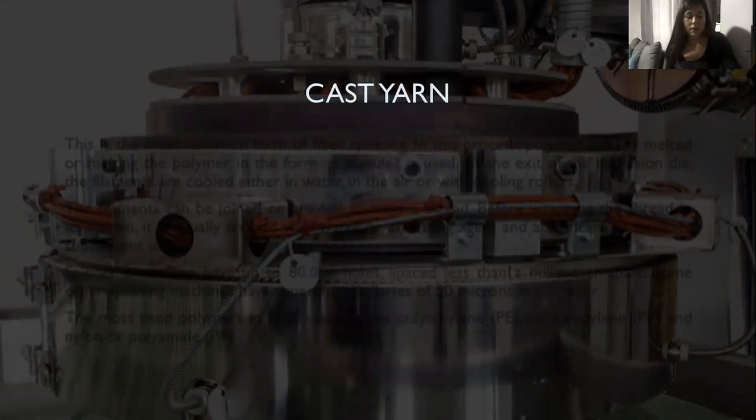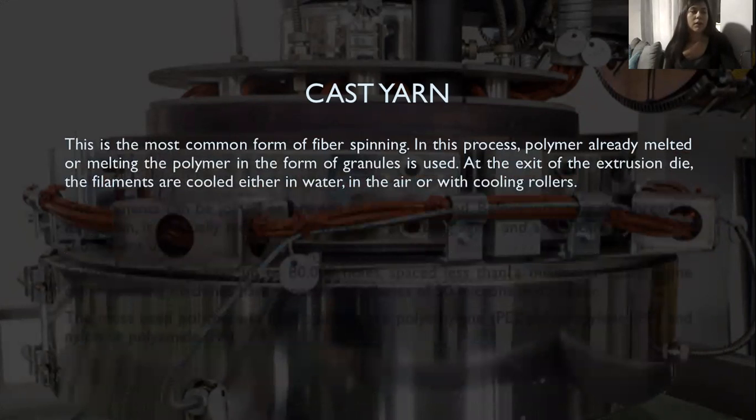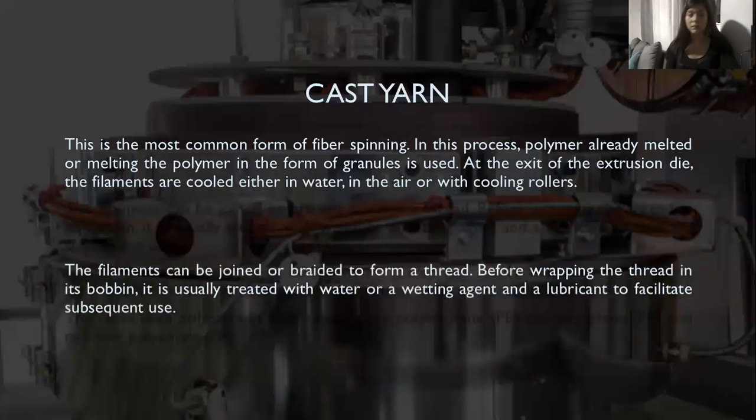We will start by explaining the melt spinning process. This is the most common for fiber spinning. In this process, polymer already melted, or melting the polymer in the form of granules, is used at the exit of the extrusion die. The filaments are cooled either in the air or with cooling rollers.